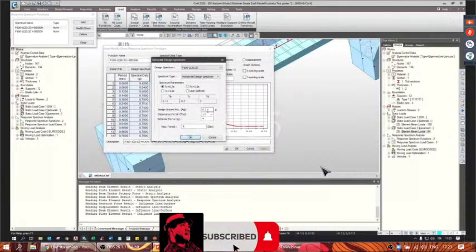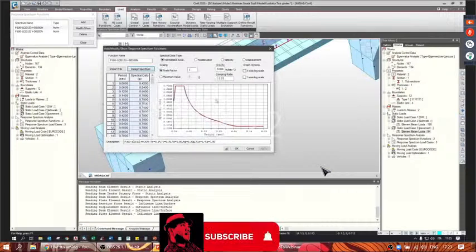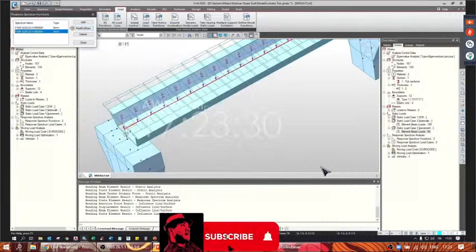of 0.3 g. This is the importance factor. For a strategic structure, we choose 1.4. And the behavior factor, as we see in the slides, is 1.5. Okay, this is how the response spectrum function appears. We also define the vertical design spectrum.